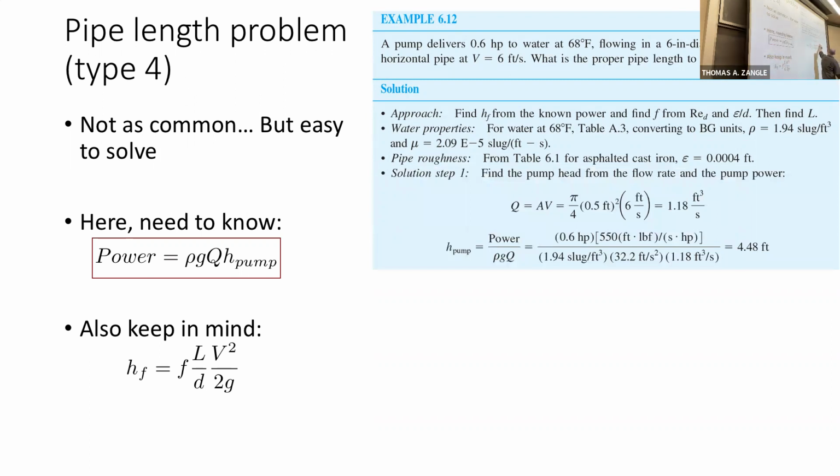If you are approaching this kind of problem, say on the exam, start by writing out what you know, right? It might not be immediately obvious to you that you know enough to plug into this power equation to find h_f. We are generally going to have to find Reynolds number. To solve one of these types of problems, you have to find Reynolds number at some point. So write out the formula for Reynolds number and start computing it, because you know that's going to be a step in solving the problem. Write out what you do know.